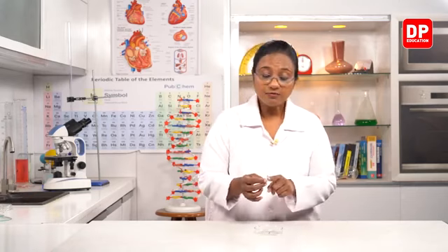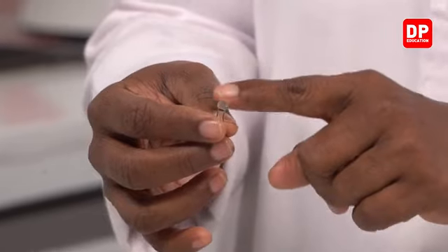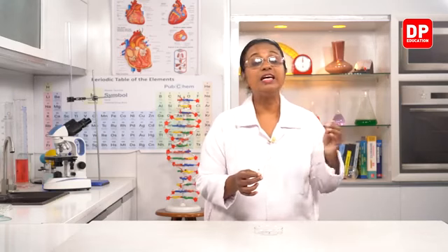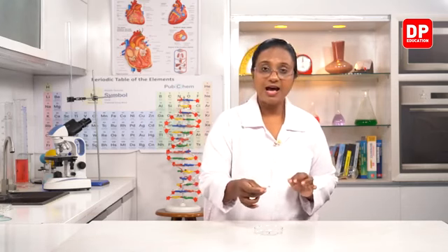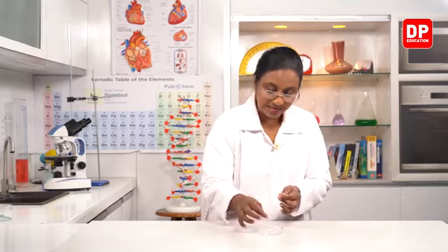But when light falls on this surface of the LDR, the resistance decreases. And when resistance decreases, there will be current flowing through the circuit. So this is used in instances where we need to change the resistance depending on the intensity of light. And that is why it is a light sensitive resistor or light dependent resistor, LDR. So you have seen an LDR, I'm sure you will understand the function.